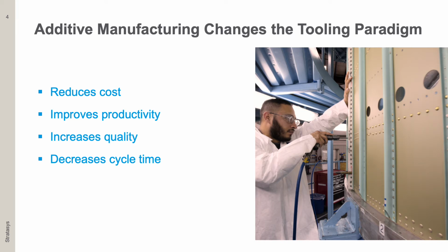Additive manufacturing, or 3D printing as it's also known, presents multiple benefits for factory floor production. Compared to traditional tooling, AM tooling is typically less costly to manufacture. AM tools can usually be produced for lower costs since only the material that's needed to make the tool is used, versus machining, where a significant portion of the material is wasted during the machining process. AM tools can also be manufactured much more quickly than machine tools because this method avoids the time associated with outsourcing and/or machine shop backlog. Being able to deploy tooling faster means production downtime is minimized, which reduces overall production costs.